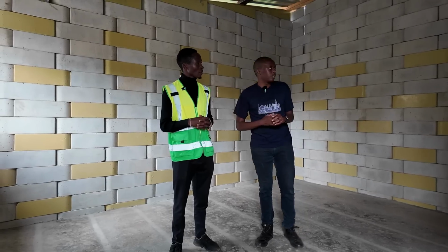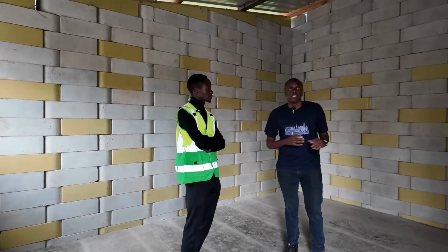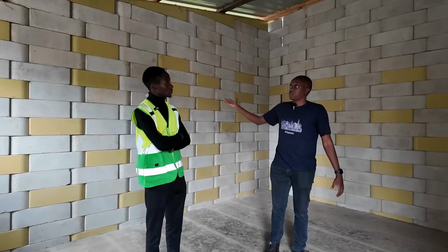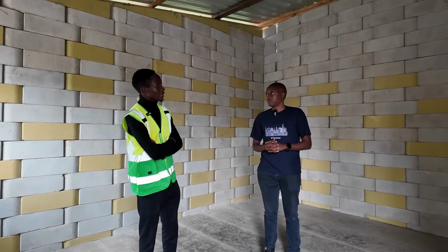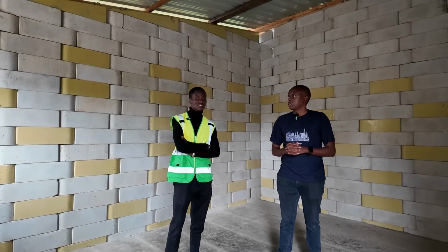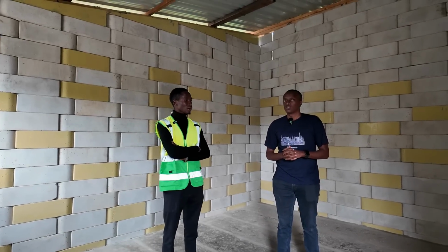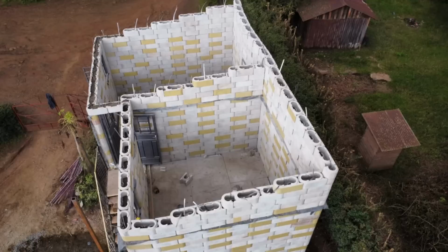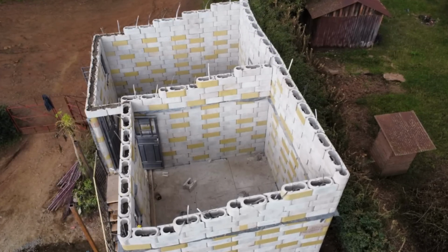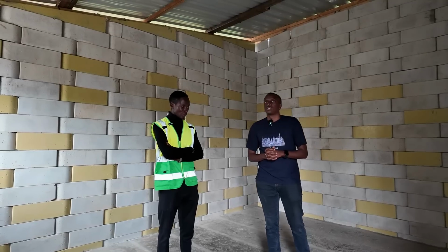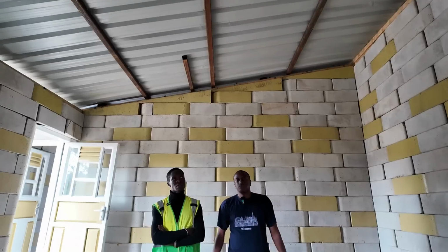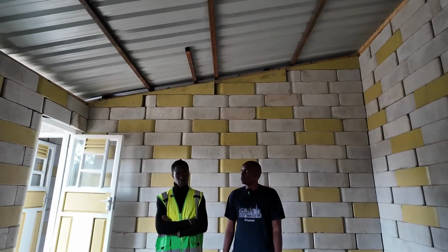Now, final question. How do you deal with corners for partitions and also for the perimeter wall? Well, the corners with partitions, it depends. There are instances where you have T-junctions. With the T-junctions, the block plans will give you a good way of how to handle it, because they'll give you special cutting for that junction. Then if you cut your blocks into the exact detail that you're given, it will be very, very easy to integrate it. The roof itself is a very, very simple roof system.